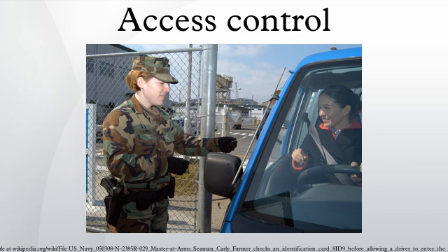The second most common risk is from levering a door open. This is surprisingly simple and effective on most doors. The lever could be as small as a screwdriver or as big as a crowbar. Fully implemented access control systems include forced door monitoring alarms. These vary in effectiveness, usually failing from high false positive alarms, poor database configuration, or lack of active intrusion monitoring. Similar to levering is crashing through cheap partition walls. In shared tenant spaces, the divisional wall is a vulnerability. A vulnerability along the same lines as the breaking of sidelights.